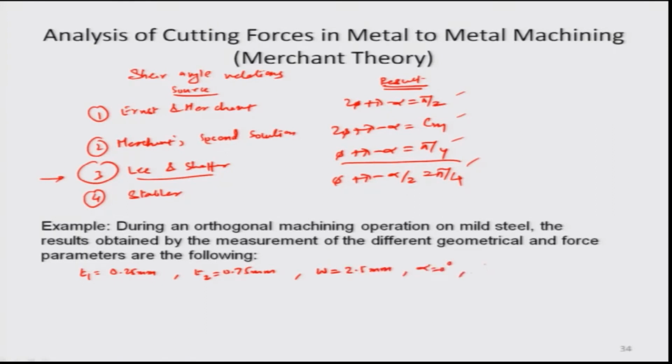So, the tool is actually almost perpendicular to the surface that it is cutting or scribing, and there are force measurements of the cutting as well as tangential force, which are acquired mostly by tool dynamometers kept near or just on the bottom face of the tool mount. The cutting force is recorded as 950 newtons and the tangential force as 475 newtons.